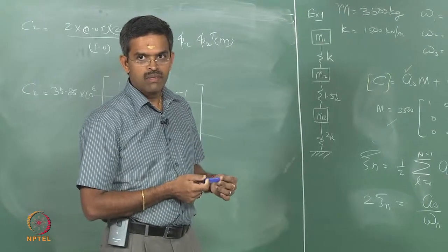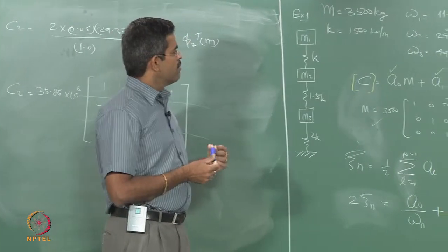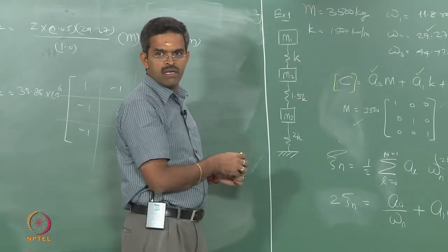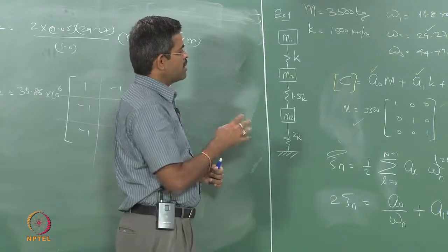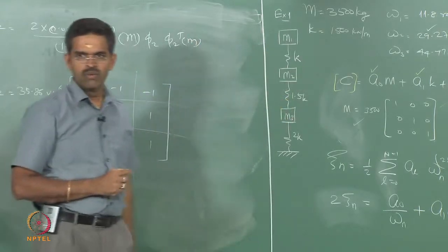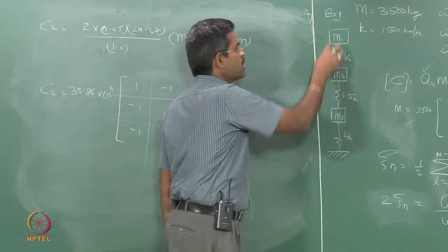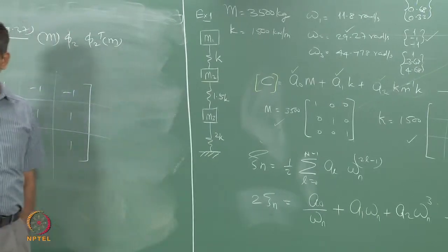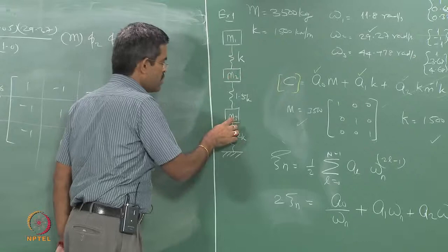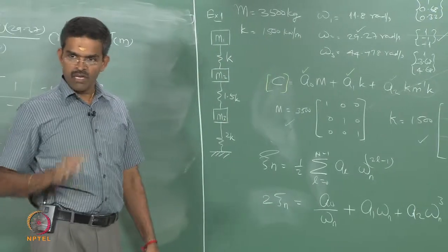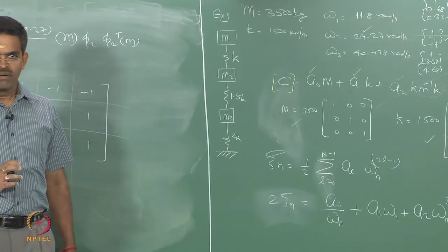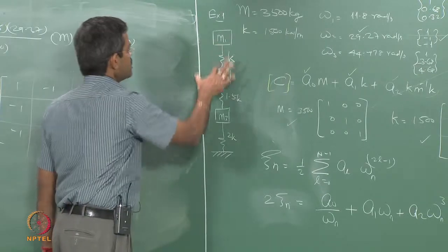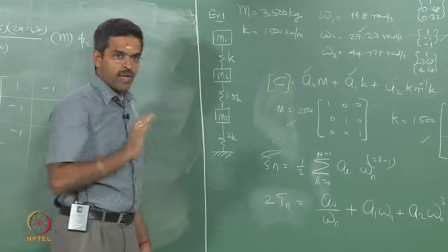Sorry? Is anybody trying to answer that there are only 3 mass points? Is anybody trying to answer there are only 3 lumped mass points? Is it so? But the lumped mass position does not indicate anything about the degrees of freedom at all. But still, in this case, there are 3 lumped masses, and therefore the 3 degrees of freedom is correct. Can you tell me why? We are considering only 3 independent displacements. Agreed. But in this example, 3 mass points is 3 degrees of freedom, is correct. Why? The answer is on the board.